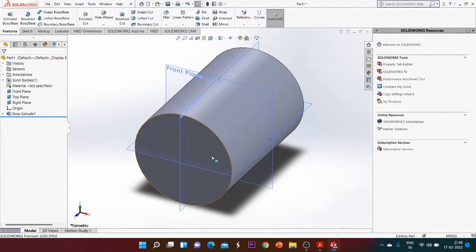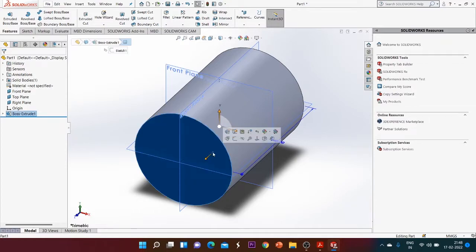On that face side, I'm selecting this face. Now you can have multiple selections while designing this. If I want to have this hole, I can place another plane at a particular face, but the easy process is to select the face and then select the command called Normal To. By selecting Normal To, it will provide me a sketch on this particular surface only.